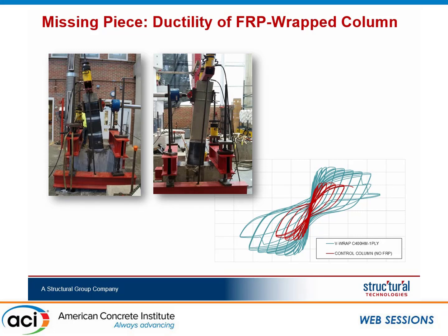He was open to that idea, but again, he said we need something like an ASCE 41 backbone curve that evaluates what is happening, and I can plug it into my platform to come up with a number. Help me with that. And that was a point where I was lucky to be involved with ACI 369. I had heard through Sergio that Sergio and his students have worked to gather all the information on jacketed columns, and they were about to introduce backbone curves for FRP-jacketed columns.